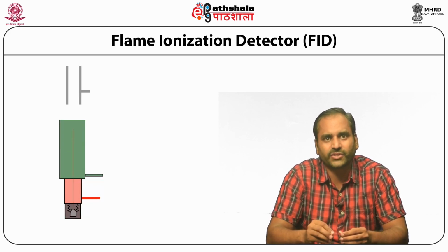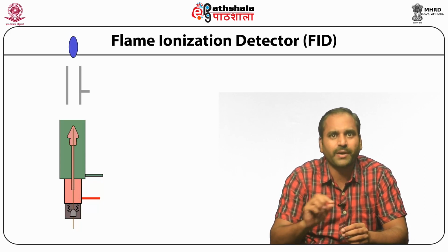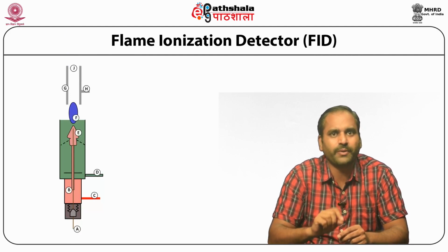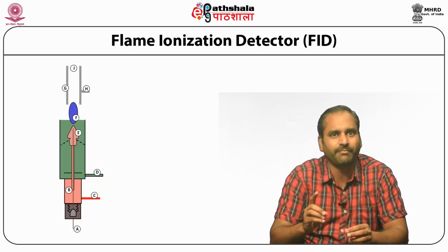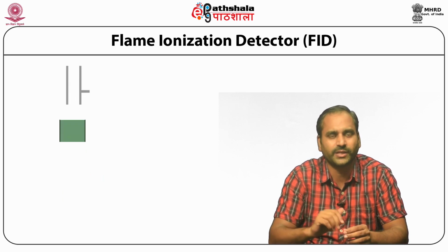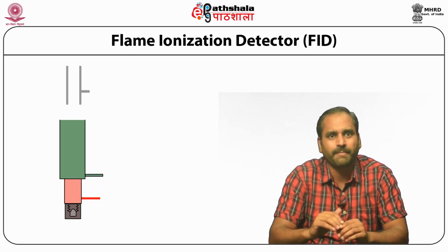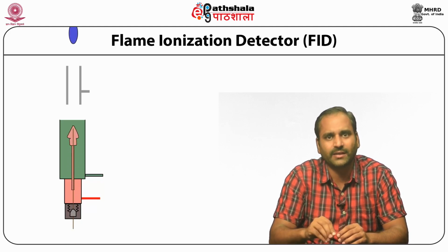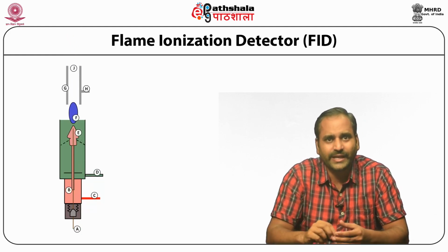This oxidant mixture continues to travel up to the nozzle head where a positive bias voltage exists, that is designated as E. This positive bias helps to repel the reduced carbon ions created by the flame, that is F, pyrolyzing the eluent. The ions are repelled up towards the collector plate, which is connected to a very sensitive ammeter, which detects the ions hitting the plates, then feeds that signal, which is being generated at H, to an amplifier, integrator